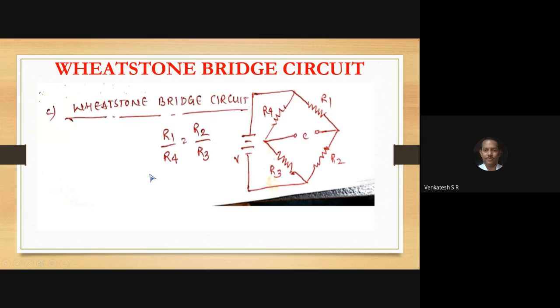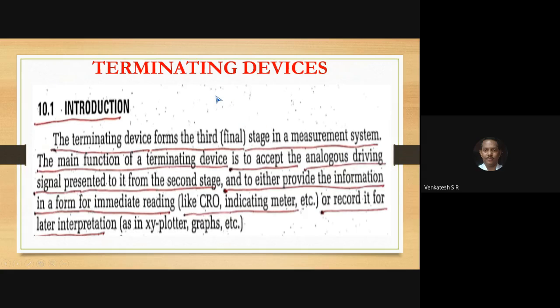Then you have to convert that ohms, the resistance units, into strain units. Like that, you can use the bridge circuit for measurement of strain in case of axial strain, bending strain, and torsional strain. Next, come to the point, very, very important.